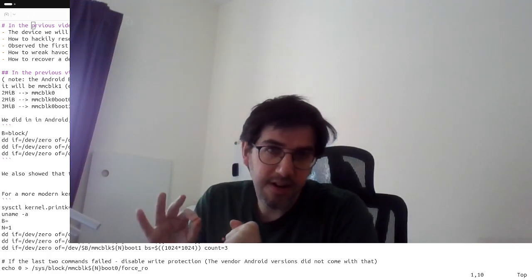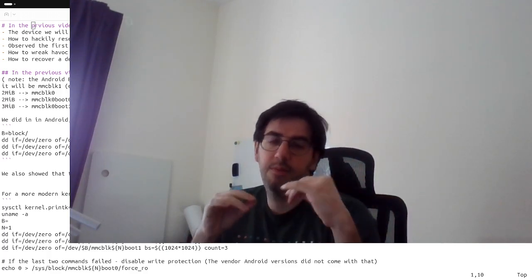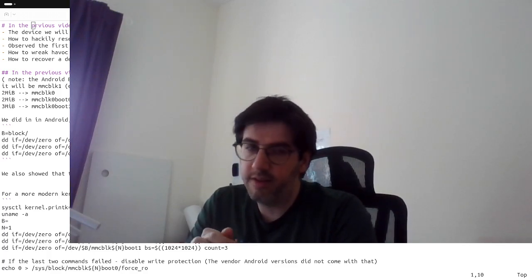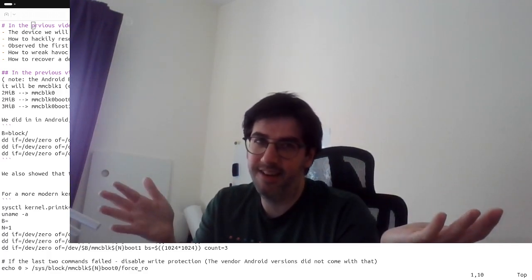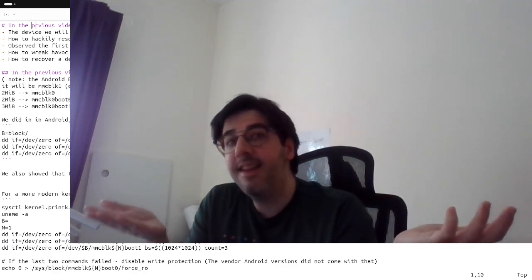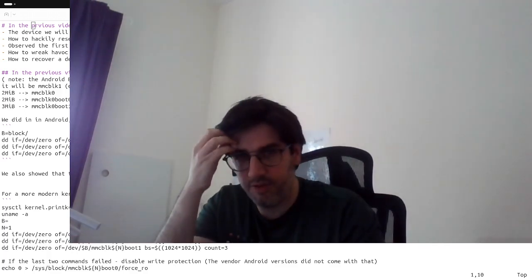This TF card and its debug abilities are not available from the boot ROM. So there are some messages that you can just have blind faith are there, but not all. They do appear if you have the right UART connector.